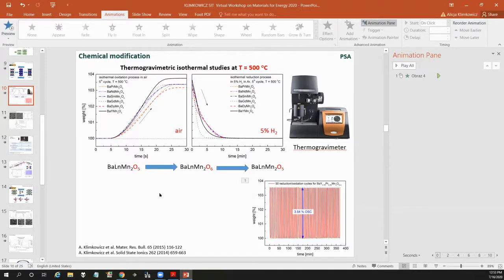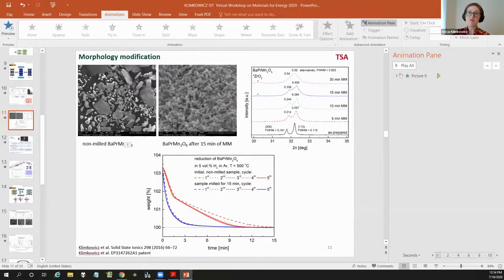So maybe if you change the specific surface area very drastically, you can clarify this. But throughout all of the work, even if I use solid state reaction and sol-gel reaction, which gives me a difference in specific area of at least one order of magnitude, I still have this proportion.